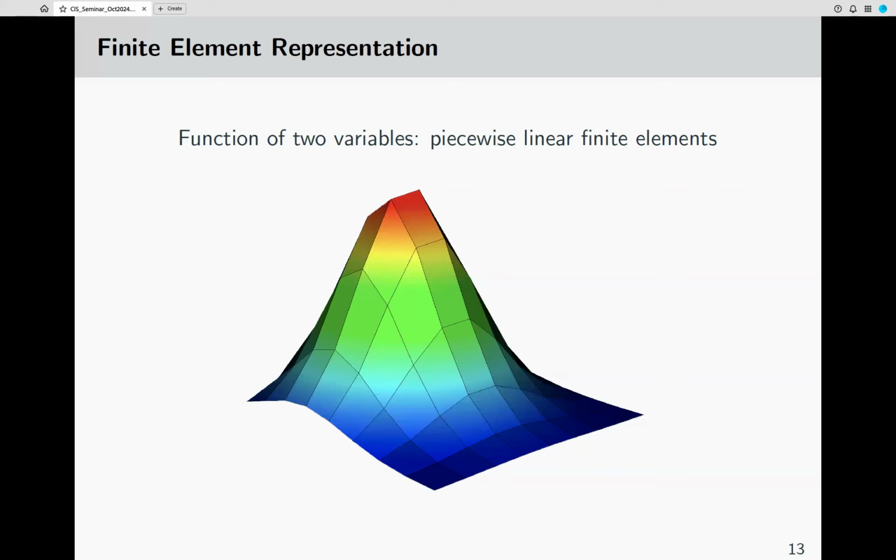In this case, if you have a piecewise linear representation, the number of variables in the linear system, so that U vector that you're seeing, is actually 128 by 1, right? Because we have one component, U1, that has 64, and the other one, 64, so you have 128. So it's relatively small. Now what we want is not something like that, which is too rough or not accurate enough. Typically you have hundreds of thousands of little rectangles to resolve things properly.